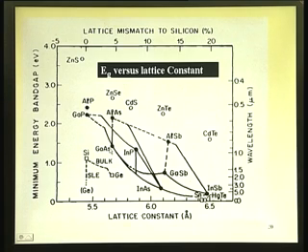See, for example, here gallium arsenide, I change by adding aluminum, that is aluminum arsenide. I mix them together depending upon how much X is present. I keep on increasing aluminum content here, it moves towards aluminum, and the entire thing, the energy gap actually changes from 1.43, ultimately it goes right up to about 2.2. Now, T is also here, this is a solid line.